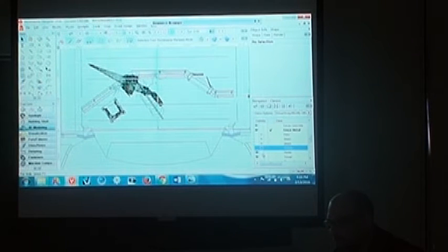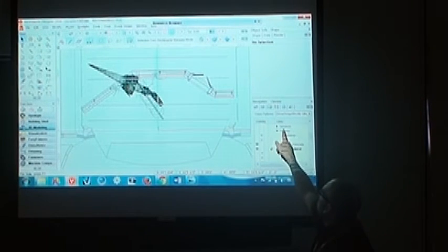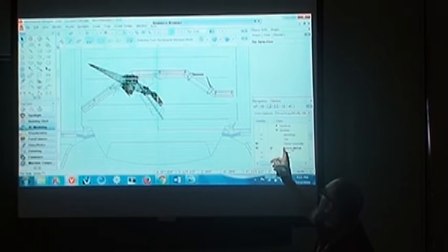Another little tip. Does everybody know that if you name your classes with hyphens in them, you get a hierarchy? See the way this class has this little hierarchy, Jurassic and then fence metal. The name of that class is actually Jurassic-fence metal with no spaces on either side of the hyphen. Each one of these classes is actually called Jurassic-backdrop, Jurassic-car, Jurassic-fence, Jurassic-floor.